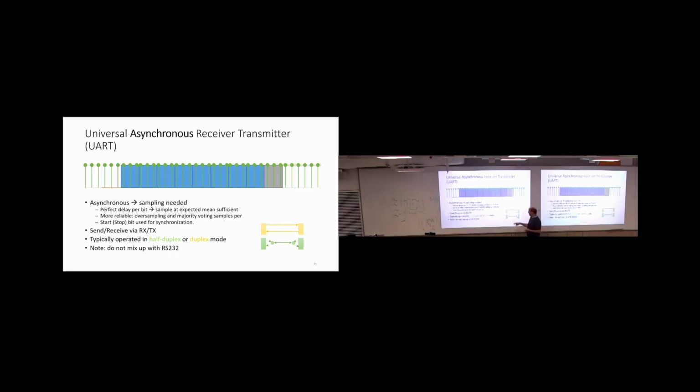That means you have here a special kind of circuitry, some tri-state, where you have something floating, and if you see one of the parties pulls down this wire in between, then this party can start communication over a single wire. That is called half duplex. You share effectively one wire.